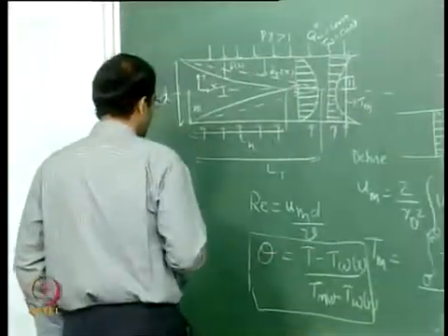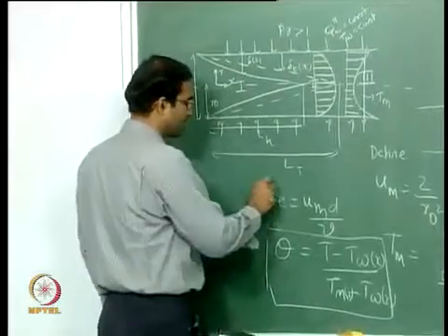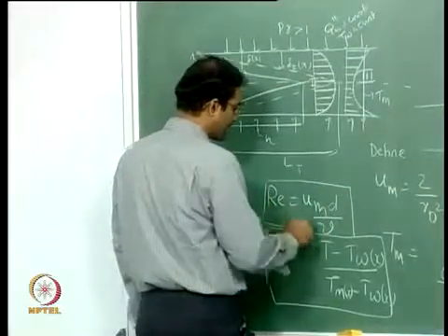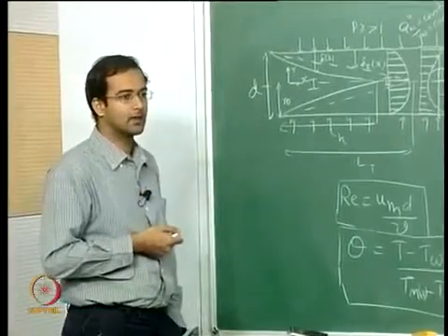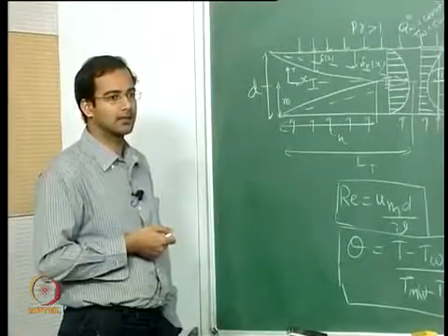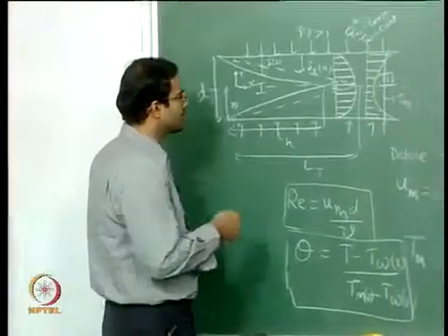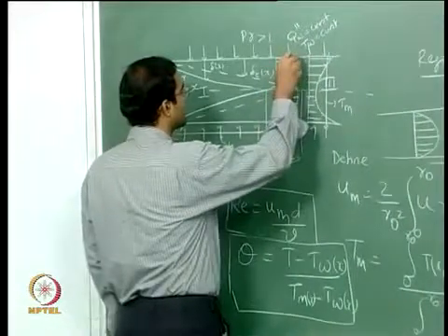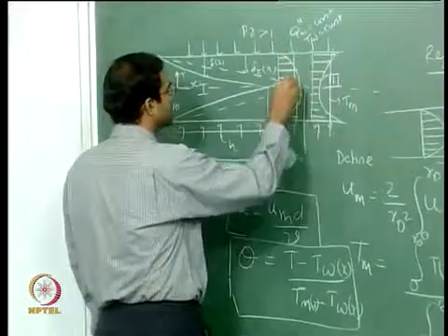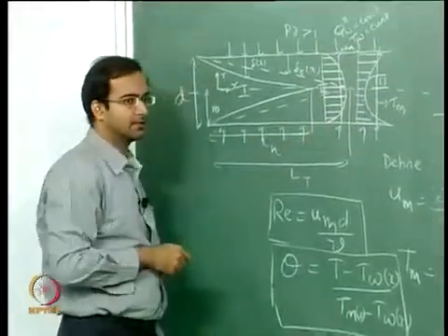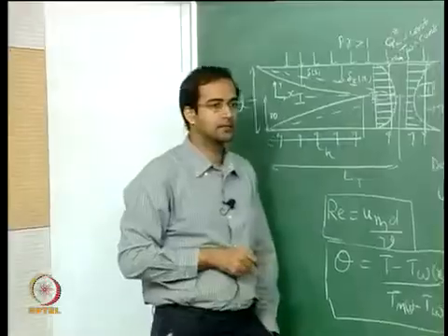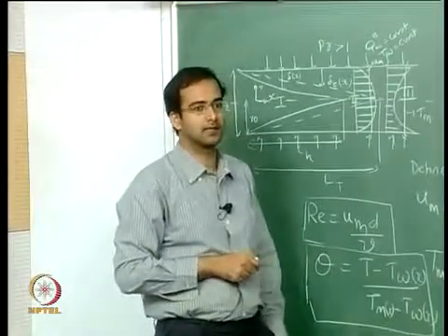And the other thing is, when you define Reynolds number in internal flows, you have to be careful that you should use another characteristic velocity called the mean velocity or the bulk velocity. So once again what it means is, if you replace your velocity profile with a uniform variation all along the cross section, it should satisfy conservation of mass at that particular location.